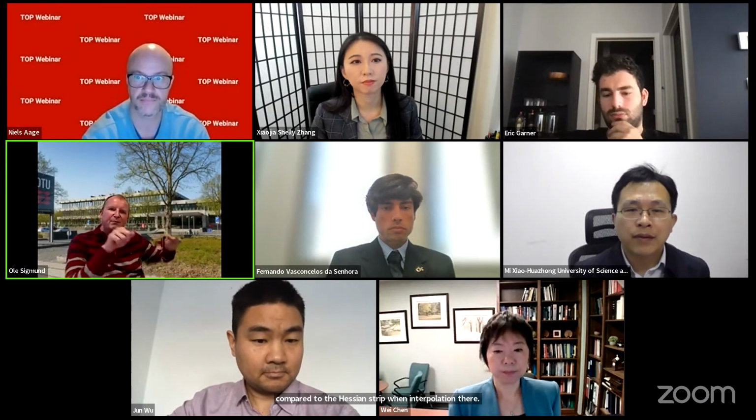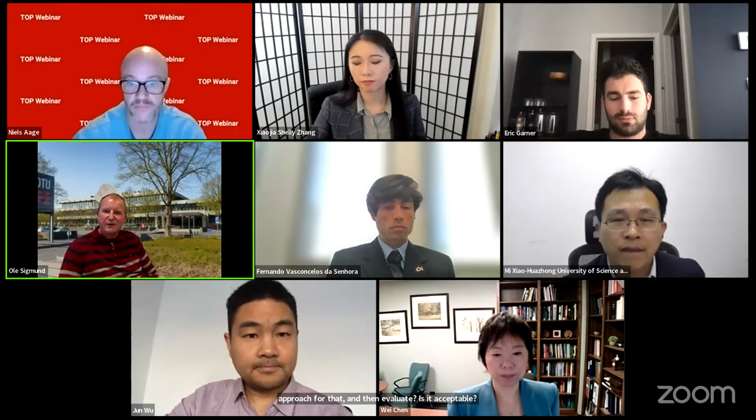Thank you, Wei. Ole, can I comment also? I think I showed here that we compare to the Hashin-Shtrikman interpolation. I think this is a good benchmark. If you use, instead of SIMP, a Hashin-Shtrikman interpolation, that should give you a benchmark for what can be achieved by an isotropic structure. Then you can compare your approach with that and evaluate: is it acceptable that we go up 50% in compliance if we introduce this and that manufacturing constraint? So I think the Hashin-Shtrikman bound is a good performance measure for other methods, and to weigh how much importance you should put on the manufacturing part.